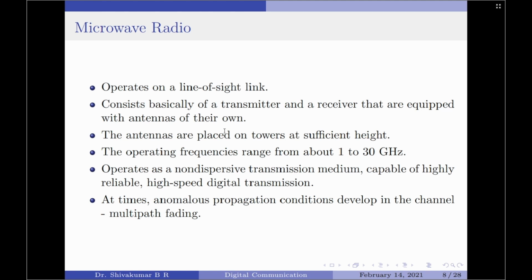The term multipath refers to the fact that the propagation between the transmitter and receiver takes place along several paths of different electrical lengths. The receiver thus sees a weighted sum of delayed replicas of the transmitted signal from these multiple paths, interfering with each other constructively or destructively. Consequently, the received signal experiences fading in that its amplitude varies with time.